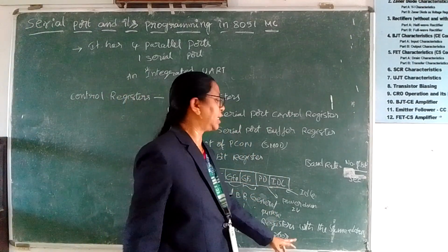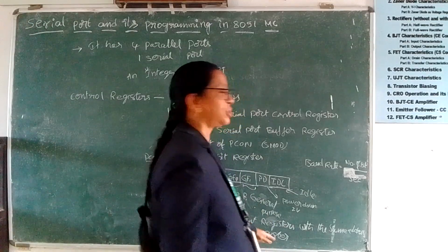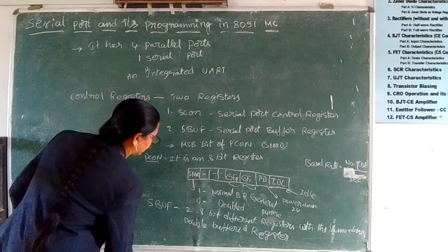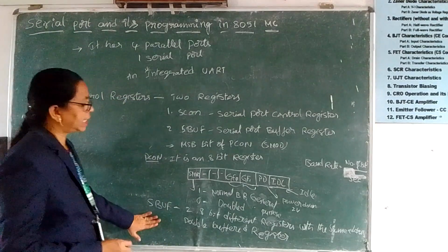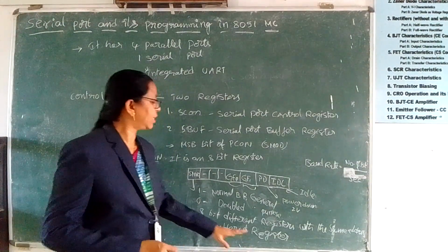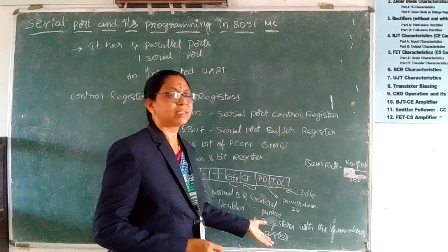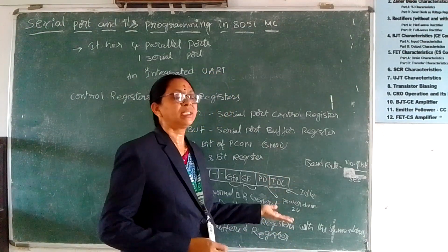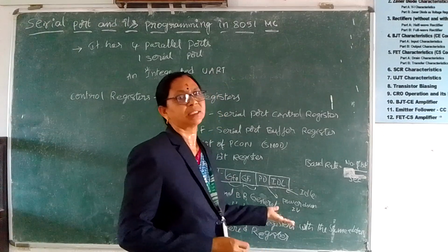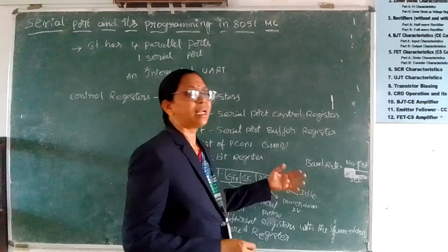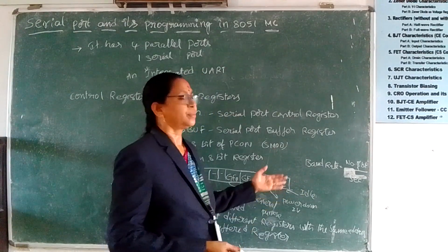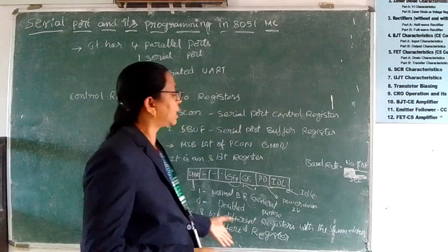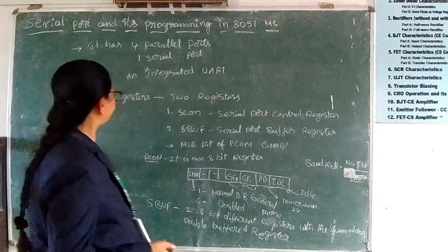One is used while reading and another is used while writing. The data will be buffered in this 8-bit register. While transmitting, this 8-bit data is converted into serial, and while receiving, serial to parallel conversion is done.